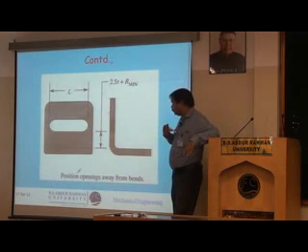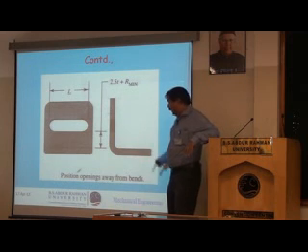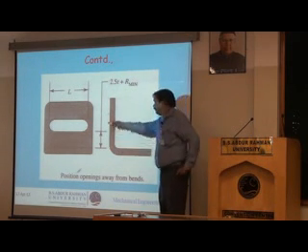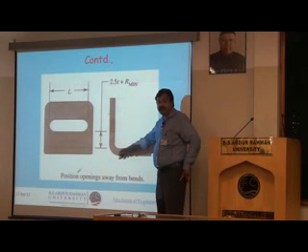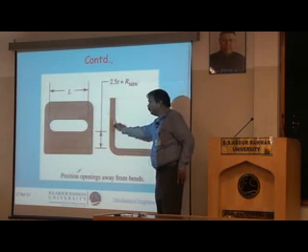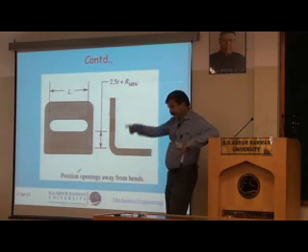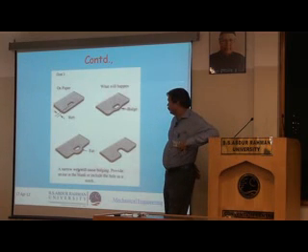Next. Again, the openings must be kept away from the bends, because this is a very weak section. It is difficult to bend a strong portion when you have a very weak portion here. It might break. Next slide please.